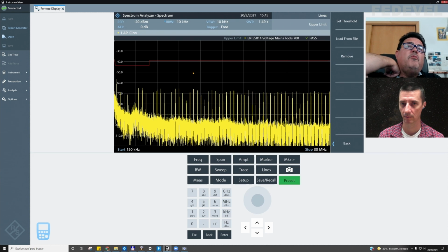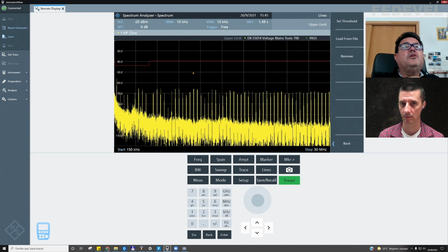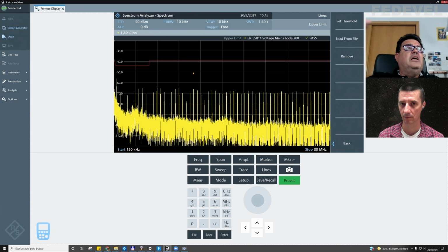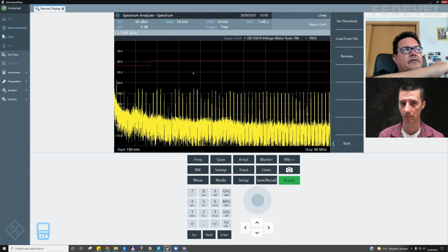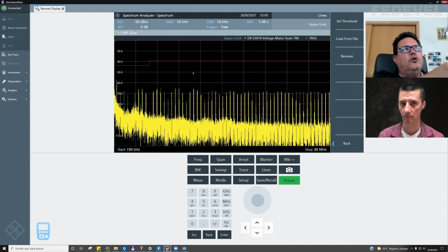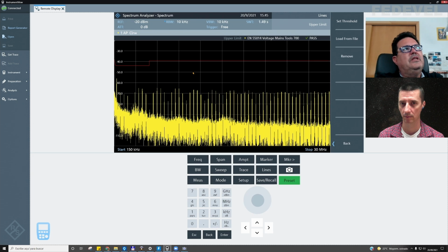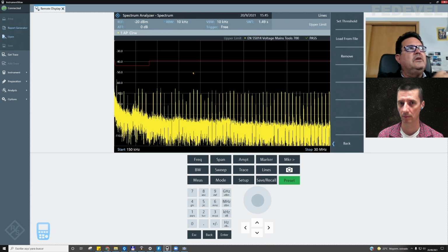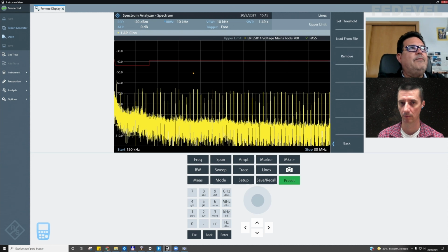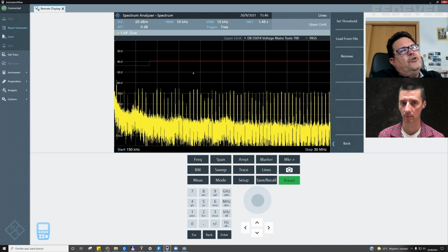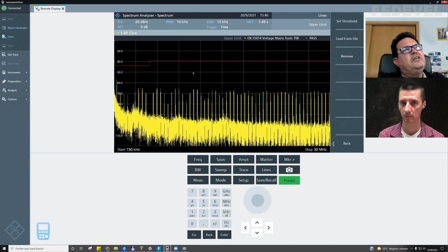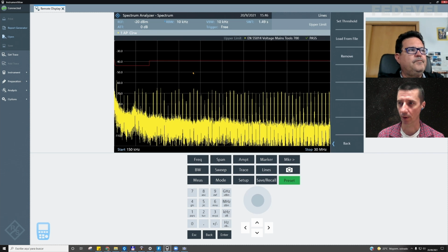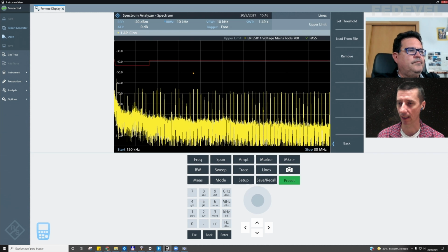And I have been working with companies that have internal limits of the company. So the internal limits are not where the official limits are. They are, I don't know, 10 dBs, 20 dBs below the official limit, to be sure that the product is perfect. This is typical from very big companies with good EMC laboratories or people. If not, for small or medium sized companies, this is very difficult. Okay, so what else can we do here in this spectrum analyzer?